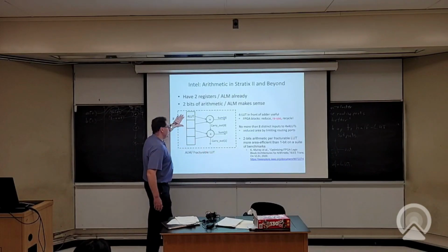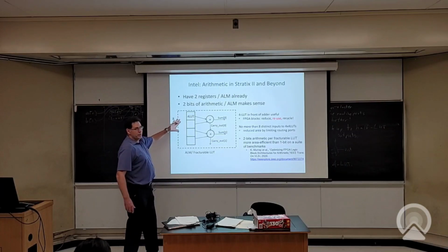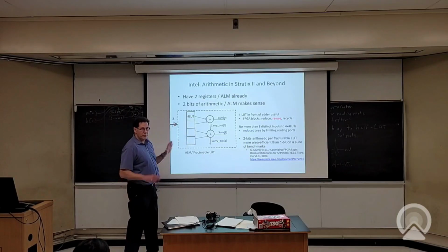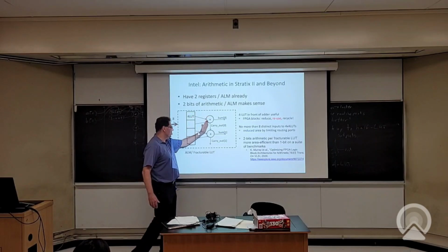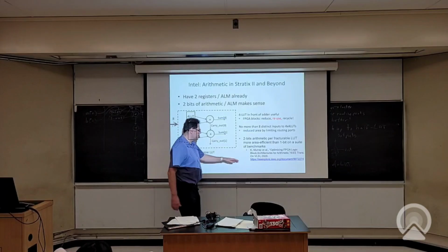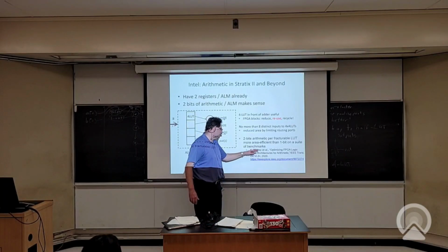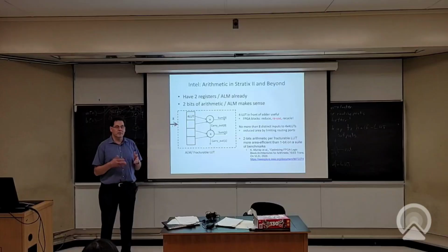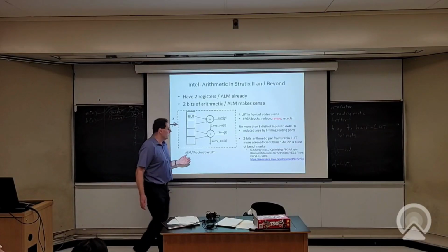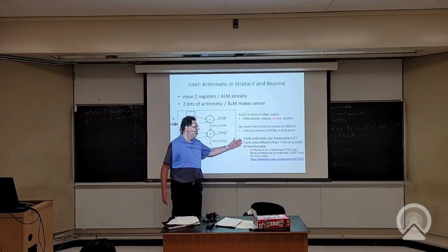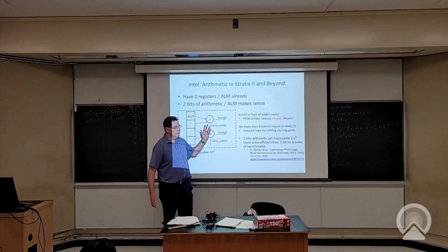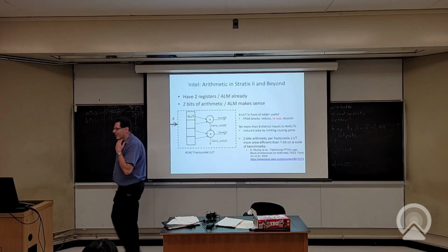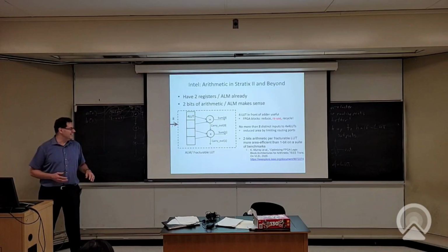And they don't add any extra routing ports, okay? So still 8 inputs coming in. They feed into these 4 LUTs that were already there, and then those feed into the adder chain. If you're interested, this paper goes through a bunch of options for how you do arithmetic, and it shows that 2 bits of arithmetic for fractional LUTs is particularly nice. And this is a difference. Xilinx does 1 bit of arithmetic per fractional LUT. Altera does 2. This paper argues that it's better to do 2, although it's careful not to draw any negative aspersions towards Xilinx.